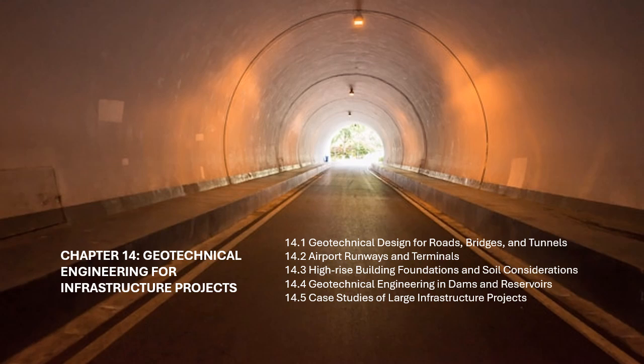Geotechnical instrumentation and monitoring. In high-rise building projects, continuous monitoring of soil behavior, settlement, and foundation performance is essential. Instrumentation such as piezometers, inclinometers, and strain gauges is installed to track movements, moisture content, and pore pressure in the soil. Real-time data from these instruments helps engineers detect any potential issues early and take corrective action if necessary.